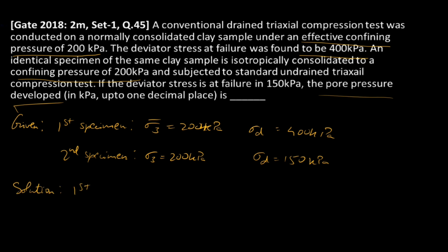So for the first sample, we can get the total triaxial stress, which will be equal to the effective triaxial stress, sigma 3 dash plus sigma d, which is 200 plus 400, that is 600 kilopascal.